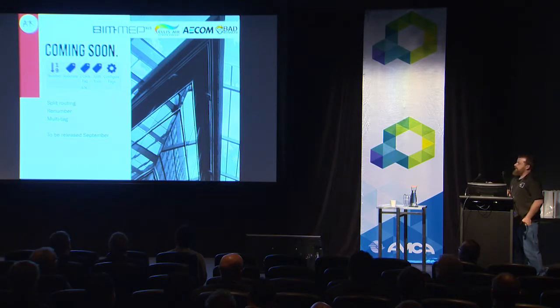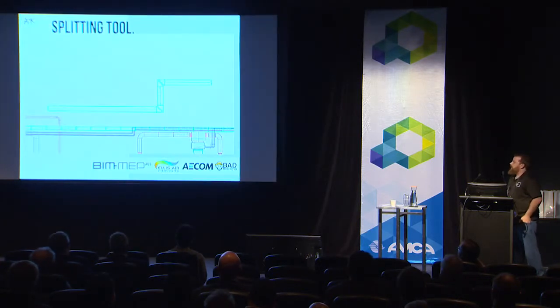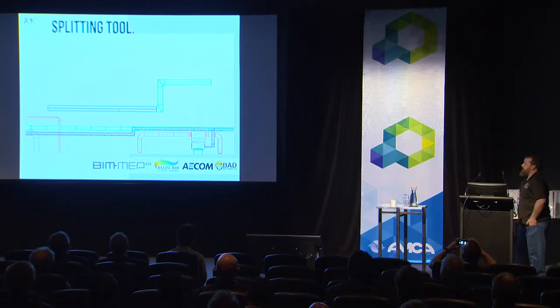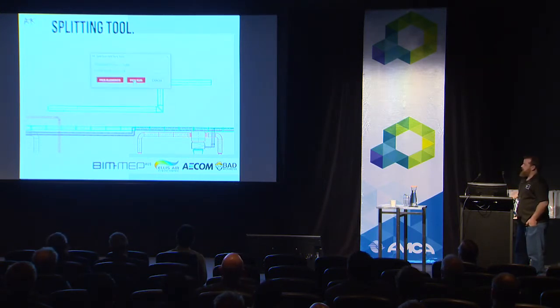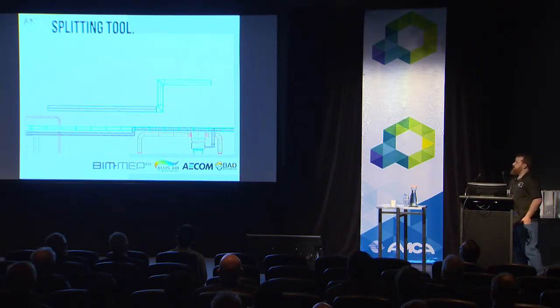So really quick, I'll just give you an overview. One of the issues that people have a lot is just picking runs and being able to split ducts by a typical length, right? This is pretty standard. And then normally you want your unions all in there too, and you just want to be able to set your size, set the actual gasket length or cut length, and be able to split the duct apart. So again, nice and simple ways to split all the runs that you need to.